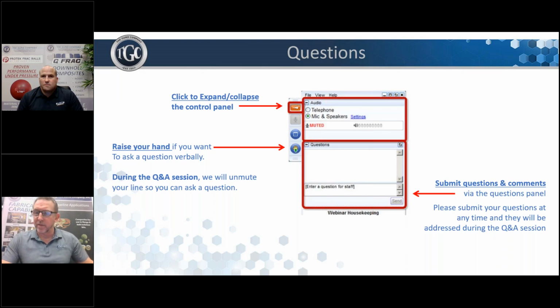We had another question come in. Kevin asked if the pultrusion rods are cured with heat or if it's just a room temperature cure. The pultrusion rods, whenever they go through the die, that is where it's heated up and cured.